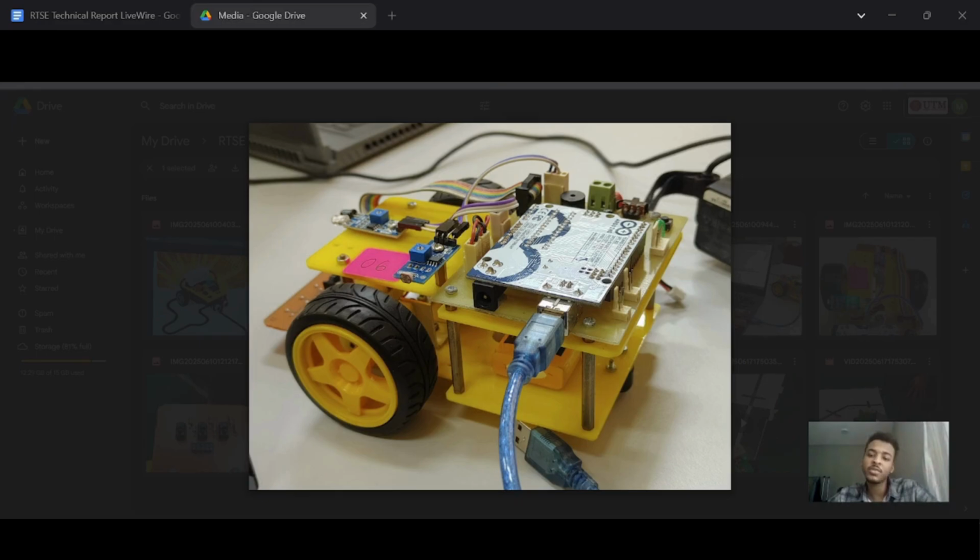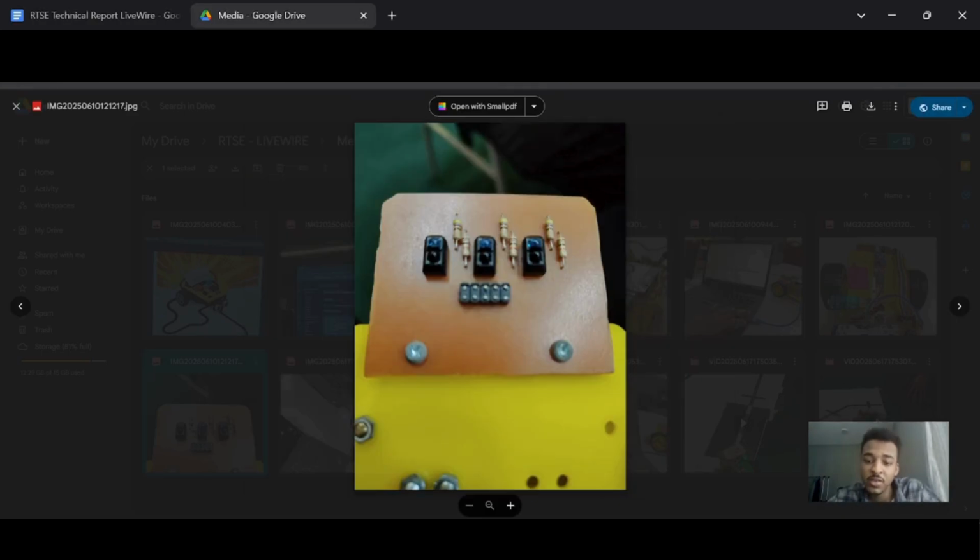For the hardware interface explanation, let me explain the hardware abstraction layer. So the interface with our MicroC/OS-II concurrent software, our RoboKar is actually equipped with three main sensors. Firstly, we have infrared line sensor arrays underneath the robot for the line detection. This provides the values from 0 to 7 that our navigation task processes every 10 milliseconds.